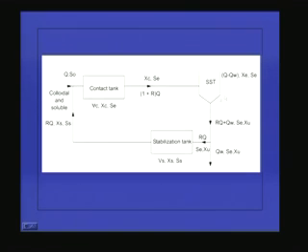Then this is the secondary sedimentation tank. If we waste the sludge from here or here, the effluent flow rate is Q minus QW, and biomass concentration is Xc and BOD is Sc.